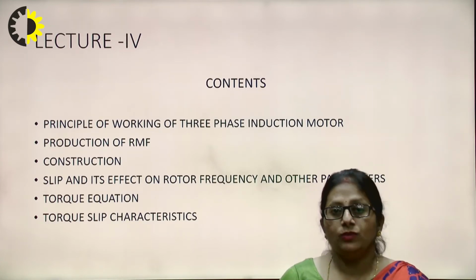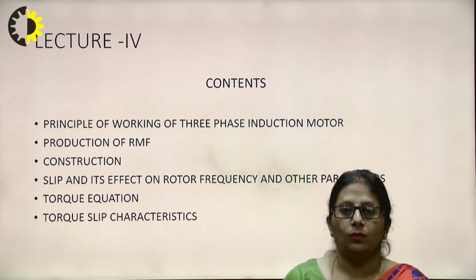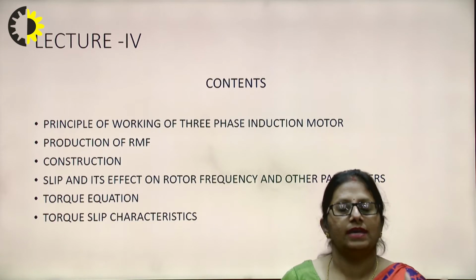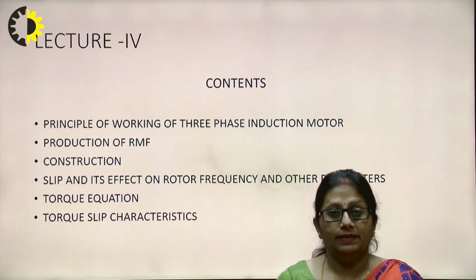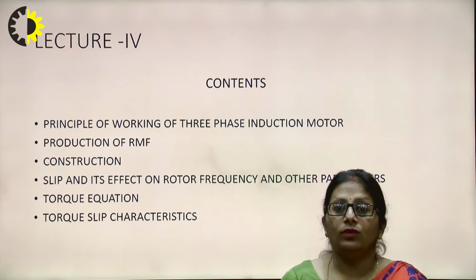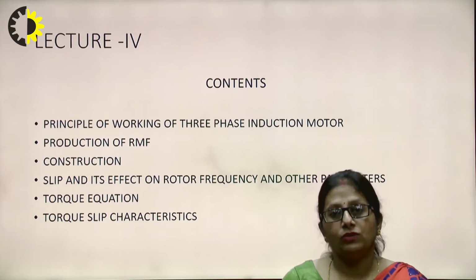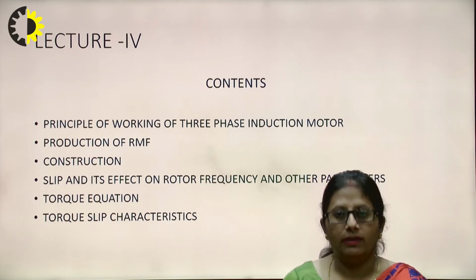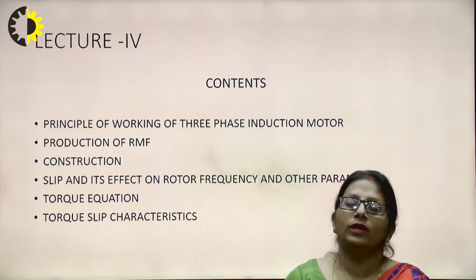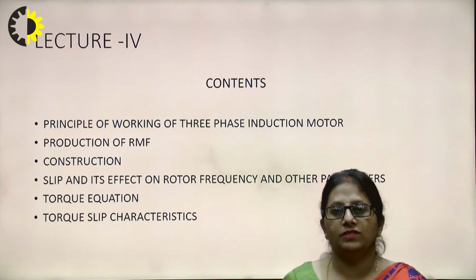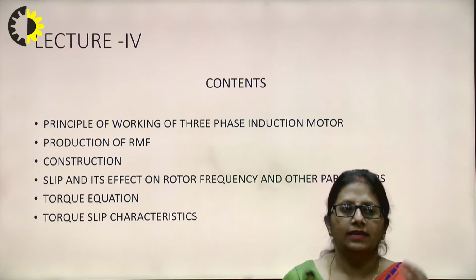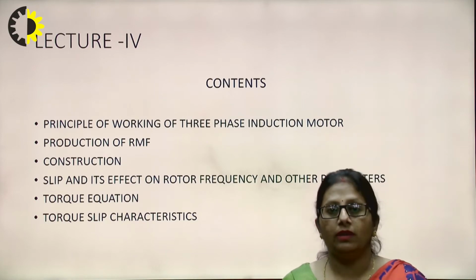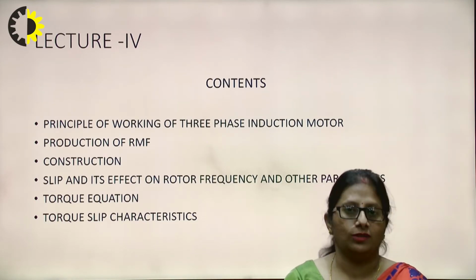Once again, coming to the compound motors, cumulative and differential. The cumulative compound has the advantage of both. It has the advantage of series, where it can be started at no load condition, and it also gives a good, moderate starting torque. So the compound motor, which comprises both, has applications such as elevators and lifts, and it can also include rolling, milling and pumping actions.